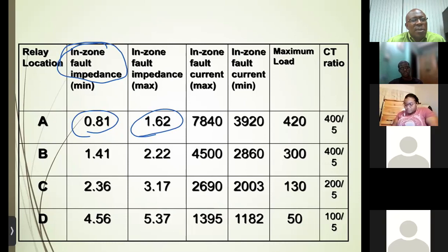Excuse me, sir. Can you hear me? Yeah, man. My internet went as you explained the 0.81. You can repeat it, please. That is with both transformers in place. So with them in parallel, the total MVA would be 150. And so the 0.81 would be V squared over S. So we get 11 squared over 150. That's how we get the 0.81.